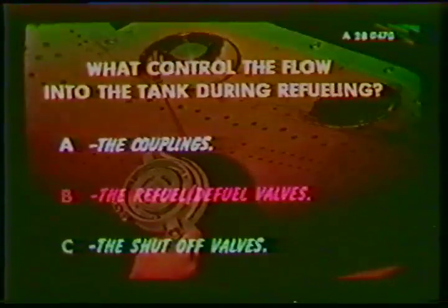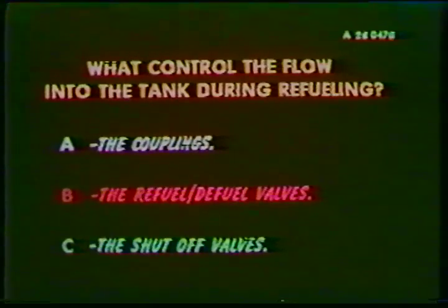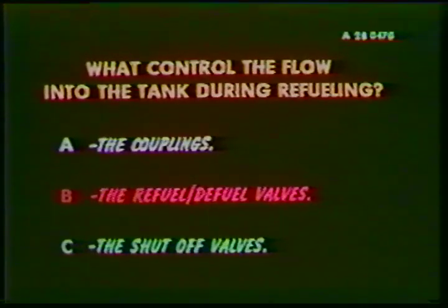Here's another question. What controls the flow into the tanks during refueling? A, the couplings. B, the refuel-defuel valves. C, the shutoff valves. The right answer is B. The refuel-defuel valve controls the fuel flow into the tanks during refueling.